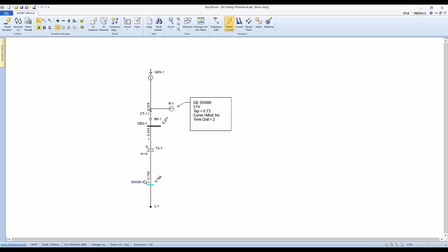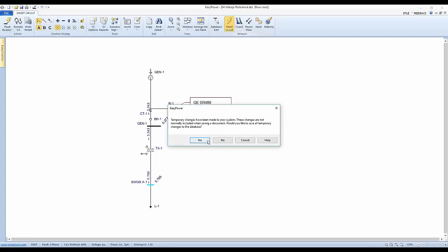So the point I want to show is, once I fault this bus, we're looking at voltage on remote by clicking on this VI, remote bus VI icon. We show that in this remote bus, the lowest voltage it'll get to is 0.27 per unit, excuse me, not volts. Well, it turns out that's about 25% of the maximum setting for the voltages.